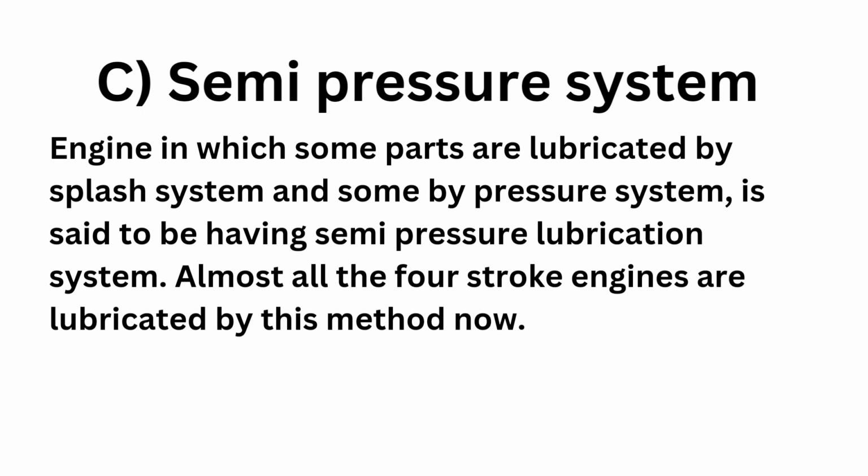C. Semi-pressure system. Engine in which some parts are lubricated by splash system and some by pressure system, is said to be having semi-pressure lubrication system. Almost all the four-stroke engines are lubricated by this method now.